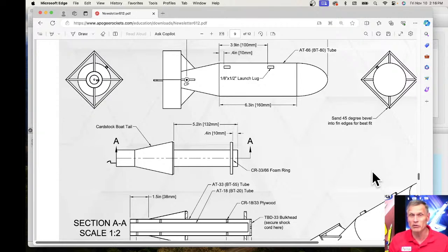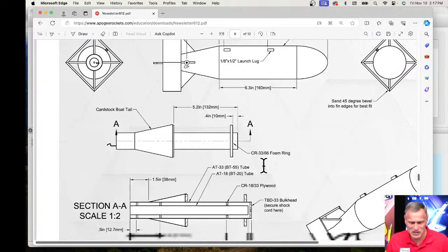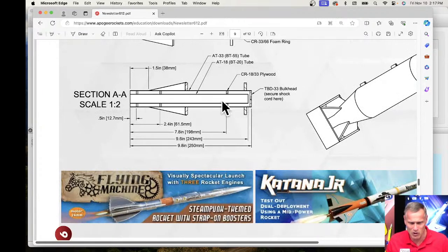So you really need to make sure your anchor points, where the shock cord attaches to the nose cone and to that ring, are really strong. Tug on them really hard before you launch the rocket, because for some reason, when that thing comes out, well, one reason is, if you look at this, we're pressurizing this small volume. Normally in a rocket, the engine mount tube ends here, and so there's a bigger volume to pressurize. You're taking the gas into a large volume, and so it's a little bit softer.